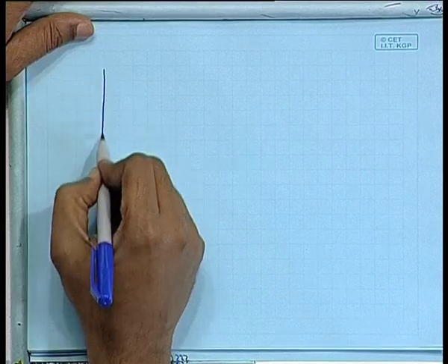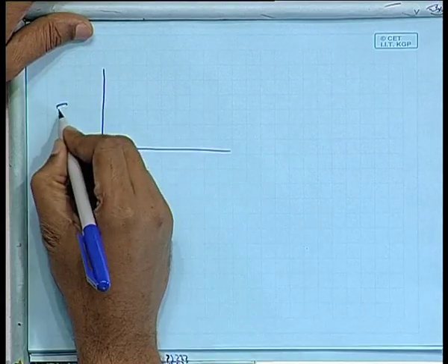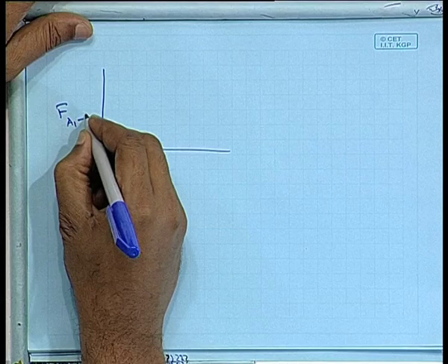So, if you have a large plate and a small plate, obviously the view factor is going to depend on R1 and R2, or the ratio of R1 and R2. It is also going to depend on D if D is the distance between the two. So, all the figures, charts, etc., which are available will give you the view factors from one surface to another, provided all these dimensions are known to you. I will just give you some of the examples, and these are available in your text. You can take a look at it and find out the view factor if the surfaces are known to you.